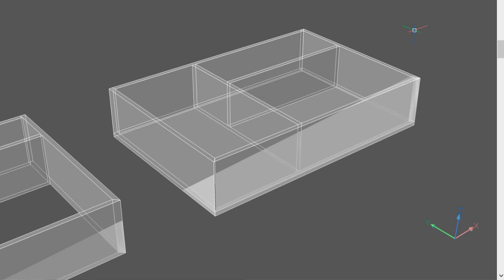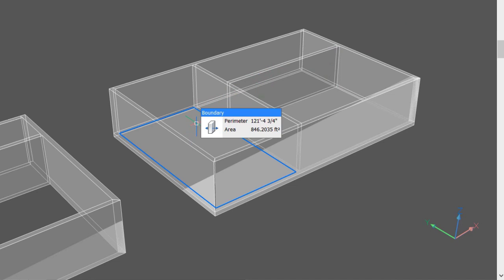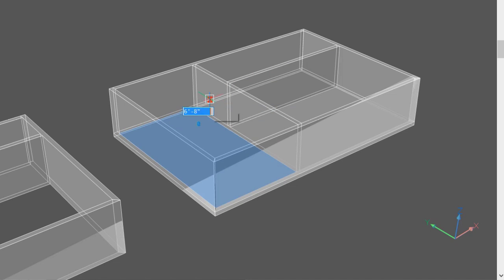We've shown all the examples on walls, but there are also options on floors and any surface. One example is selecting the boundary on the floor. We can easily create a floor of the same footprint above. If we highlight the full floor surface and select BIM Drag, then we have the same options as were displayed when working with the wall.